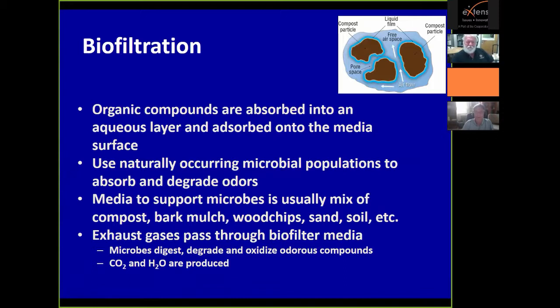And that biodegrades the material. For indoor facilities where you have a lot of diesel equipment running around inside the building and you have carbon monoxide emissions from the engine exhaust, you probably need a longer gas residence time to biodegrade the CO.